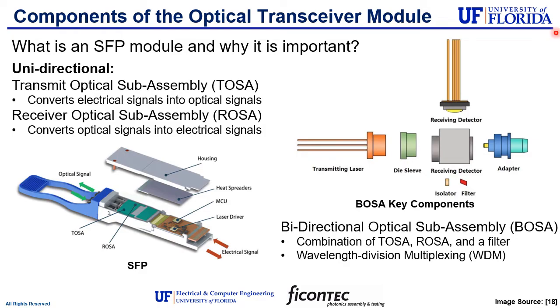Now, the PCB's housing protects the entire device and defines the form factor of the product, and the pluggable pins on either end enable hot swapping, so the transceiver can be plugged in anywhere onto a server system. Now, additionally, there are heat spreaders that are mounted across the assembly near key components like the laser driver to draw away heat and give the device a boost in efficiency.